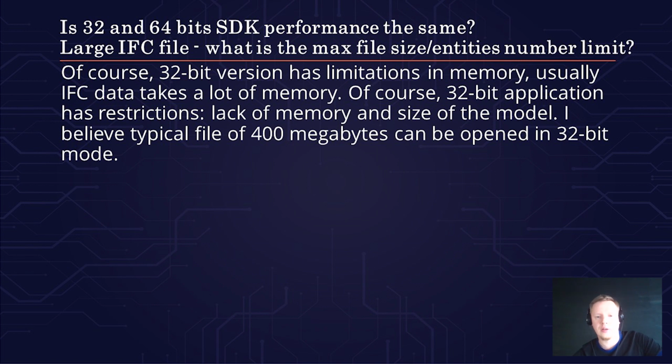Usually, IFC data takes a lot of memory, so of course, a 32-bit application has restrictions on memory and size of model. I believe a typical file of 400 megabytes can be opened in 32-bit mode.